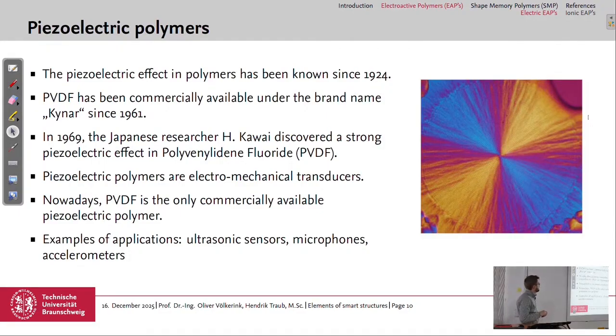And PVDF is a material which has piezoelectric properties, at least in a certain state, like the piezoceramics, where you need this special lattice structure, so not the cubic lattice, but a rhombohedral, for example. And also PVDF has to be in a certain phase to have piezoelectric properties. We will have a look on that.